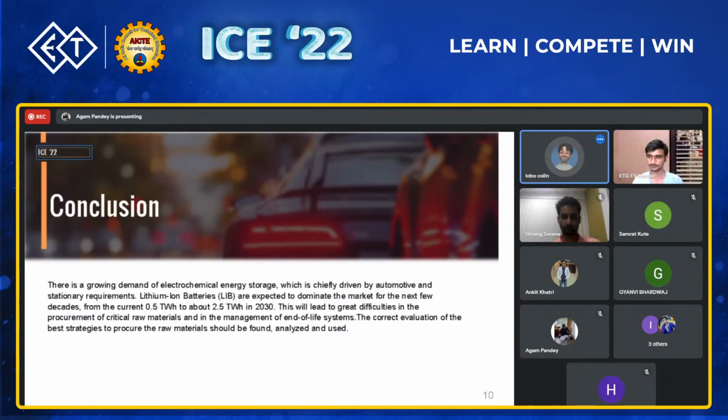The way I compared it was cylindrical versus pouch. Now, if you consider a pouch, it might be beneficial in some areas, but the weight increases. But with cylindrical, the weight reduces. There is research which shows a significant reduction in weight, around 500 kilos reduction in the whole car's weight. That is almost 1/3 of the car weight. So I thought, why not use lithium ions? Availability is also better. Yes, very good.